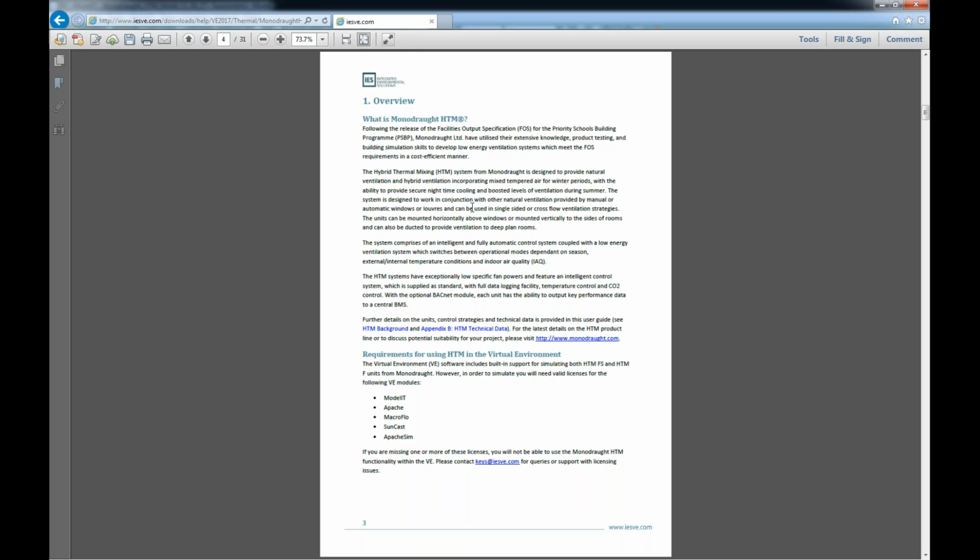However, obviously some people do like to have a little bit of self-control over the level of ventilation coming into the room, so within that we can also provide manual override inputs. If the user wants, they can increase the level of openings to the space, increase the fan speeds, or turn the systems off completely if they're feeling it's getting too cold below their preferred levels of comfort.